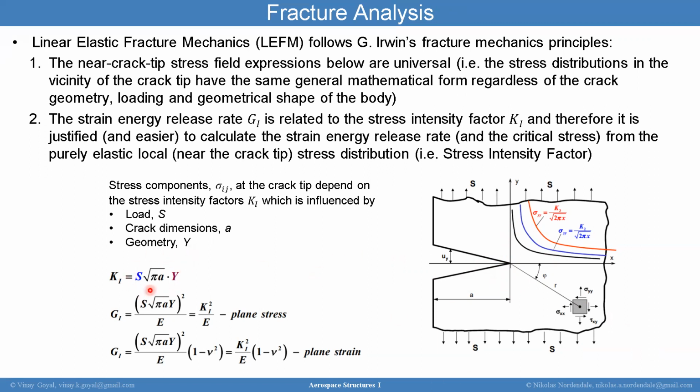You can see here that the stress intensity factor equals the load that you're applying, the square root of pi a. A is the crack geometry, for example, and Y is a geometric factor. It depends on the geometry of the configuration you're studying.